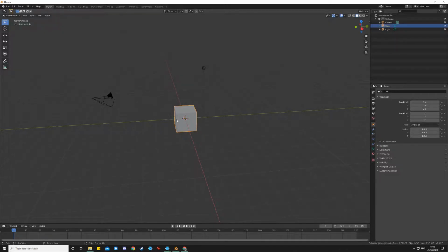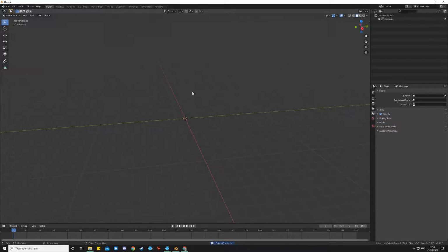And then you're in Blender, like here, and the first thing to do is we've got to import our model from Meshroom. So within Blender, whenever you open Blender, you're always given a box and a camera and a light. You don't need any of this for what we're doing, so we need to delete all this to start with. So we press A, which selects everything, and then we press X, or you press delete, and you say, yes, I want to delete it, and we've got a nice clean space here.